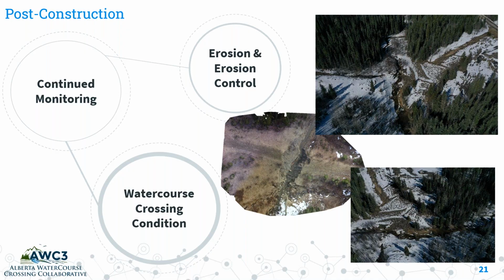Well, if you want to keep on measuring how effective your erosion control measures are, you could have a drone pilot go out like once a quarter, fly the area, and using the post-processing imagery software, you can extract the volumes of the slopes and see, okay, we can see that X amount of sediment has actually entered into the watercourse, or we can see that, hey, very little to no sediment has entered. Our erosion control measures are really working here.